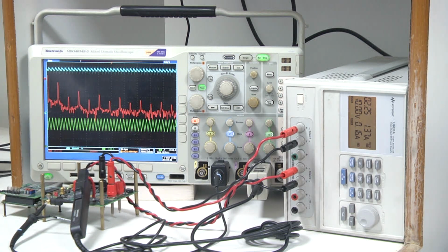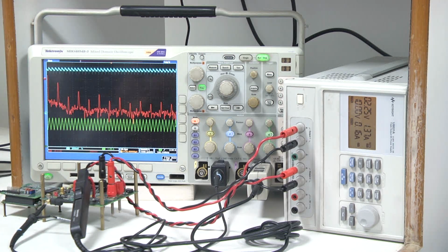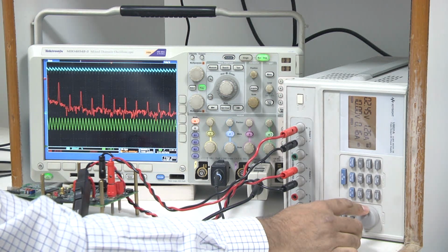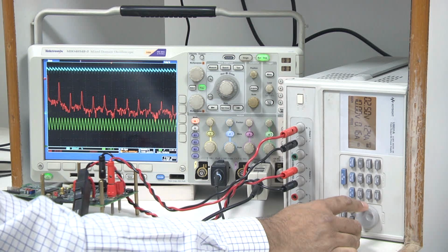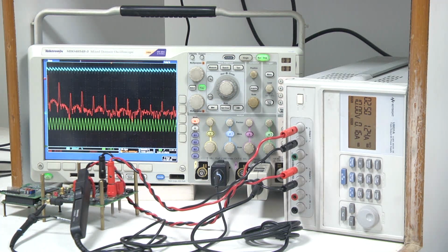Because if you talk about constant off time, since the off time is fixed and the falling slope is V0 by L, and since V0 is more or less maintained, the ripple is maintained, so the ripple is not changing. That's why we discussed that this will be a very good example for an LED driver or similar, where you want precise current regulation. Now if you go to 2.5 volt input, then it is perfectly stable and the switching frequency is slightly above 250 kilohertz.